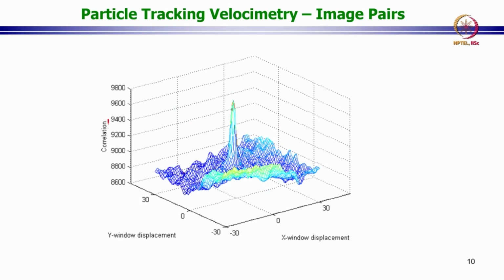You can also do the correlation based tracking, and once again you can see this is the 0 0, and here instead of a minima you actually get a maxima in the correlation, and this becomes clear when you look at the mathematical expressions. The correlation phi is a negative of d. So, that is why it has a positive value in this particular case, and the maximum here corresponds to the displacement.